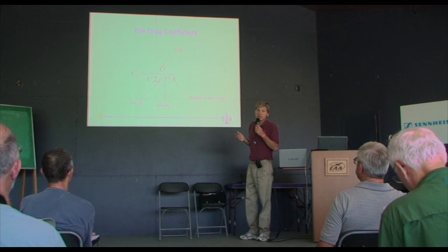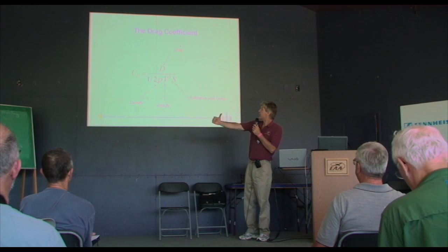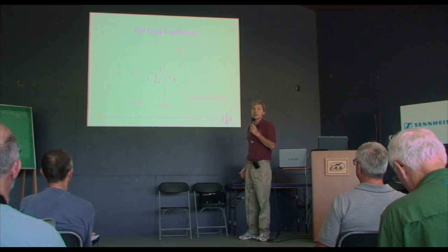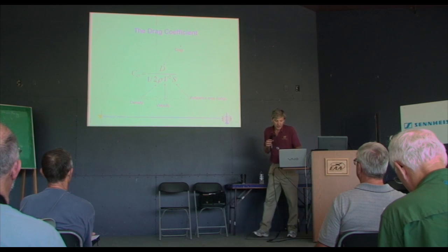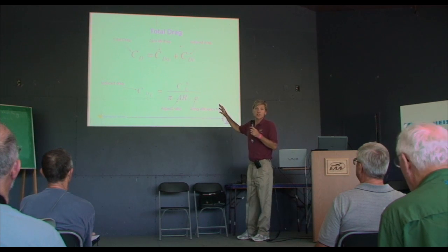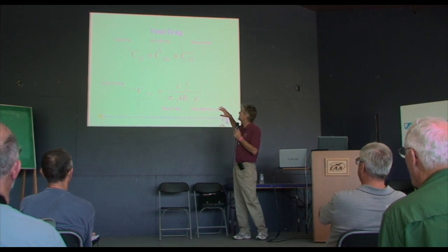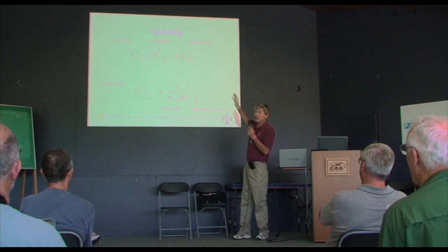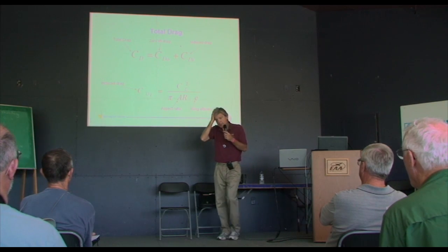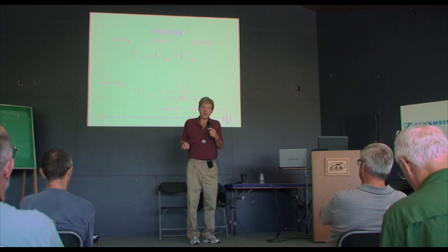The drag coefficient is merely the drag. Lift is going up, drag is going back, and it's merely the drag force divided by the same thing. So again, a very common starting point. The total drag is a mixture of two things: the zero lift drag and the induced drag. Now the induced drag is a drag that is strictly a product of the lift. If you have no lift, you have no induced drag.